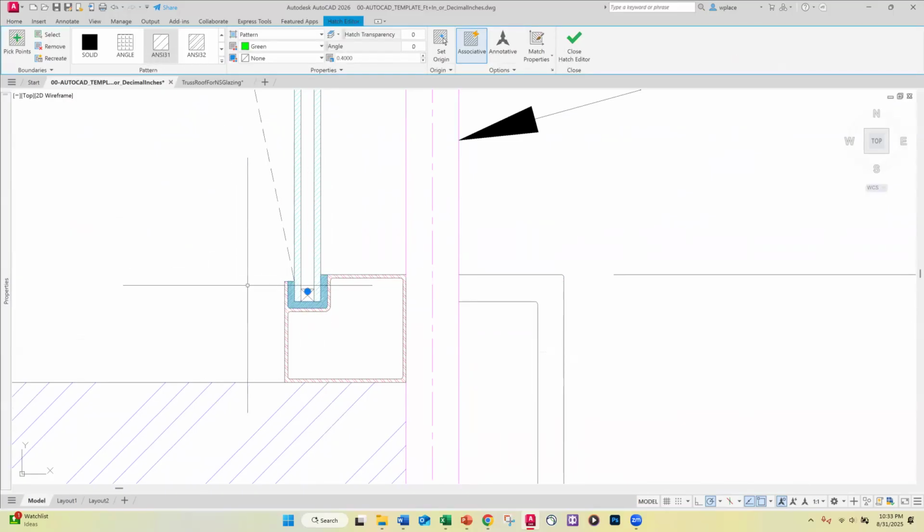And one of the things we do with this neoprene is we bring it up higher on the inside. So if water runs up against this glass and tends to pool there, that water cannot get inside the building here because gravity is keeping it from doing that. This is a 3/4 inch interface here, which is what we typically say is the minimal amount and the appropriate amount when you're trying to grab hold of glass and keep it from moving around and maybe getting sucked out under wind suction.